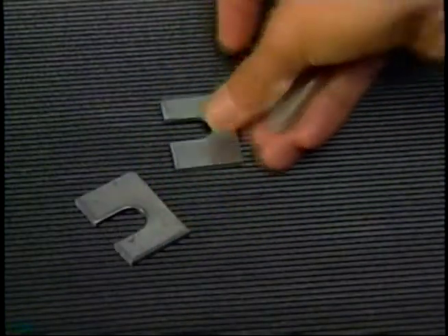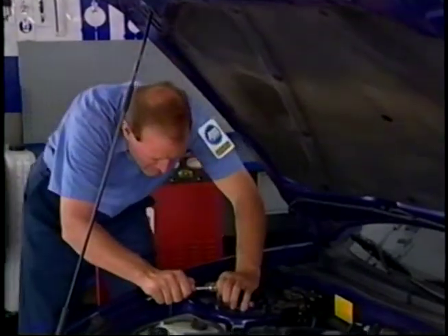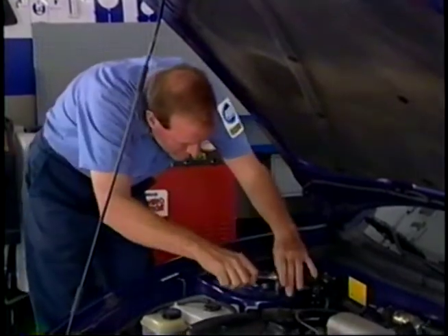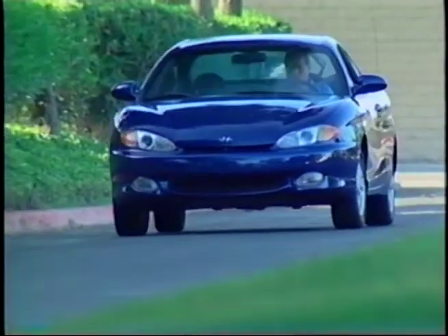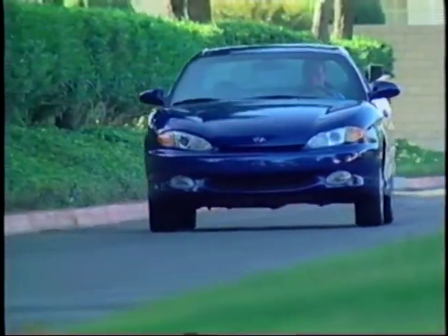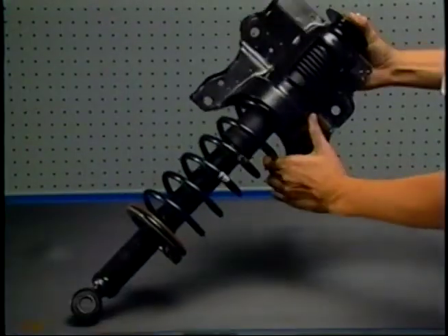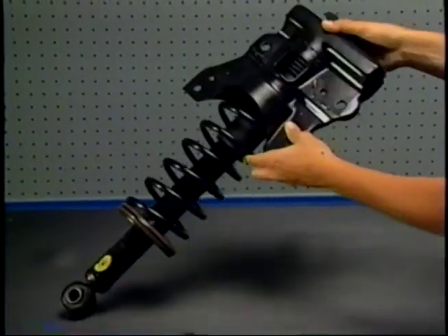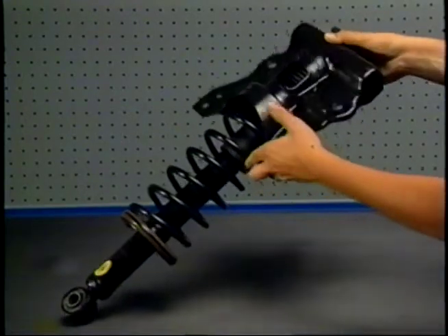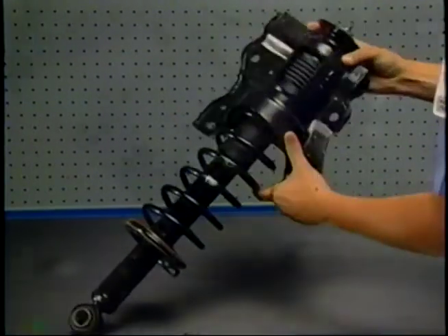Where camber is adjustable, it is usually adjusted using shims or cams on the upper control arms. Camber is usually not adjustable on front-wheel drive cars. Where it is, the adjustment is made by moving the position of the front strut in its mount. Caster will not cause tire wear, but will cause problems with steering effort, wheel shimmy, wandering, and pulling during straight-ahead driving. If you're troubleshooting a caster problem on a front-wheel drive car, remember caster is not adjustable on most of today's front-wheel drive vehicles. Inspect the suspension for bent or damaged parts and replace them to correct out-of-spec conditions.